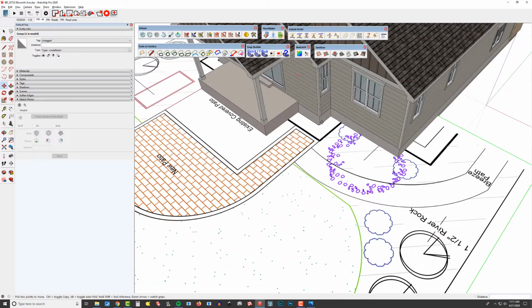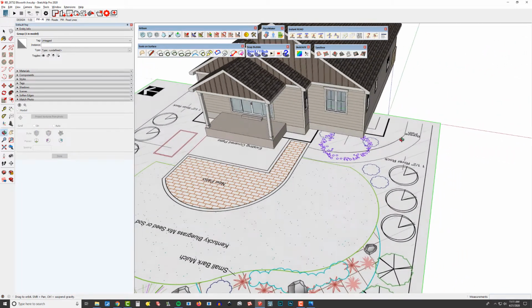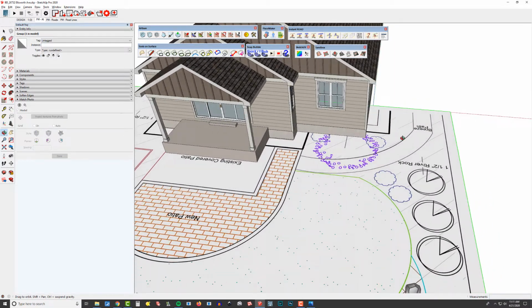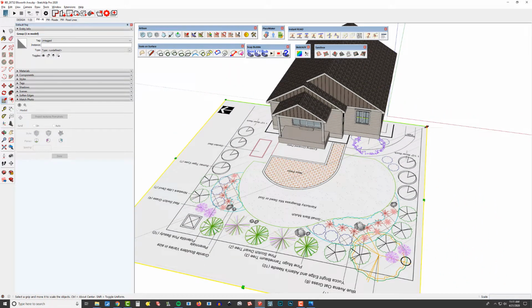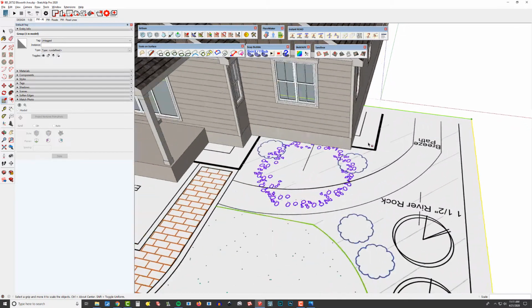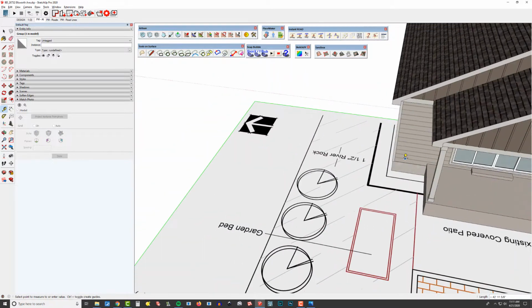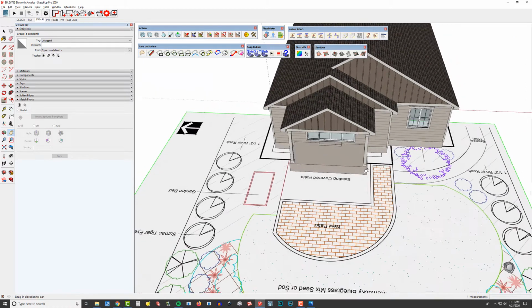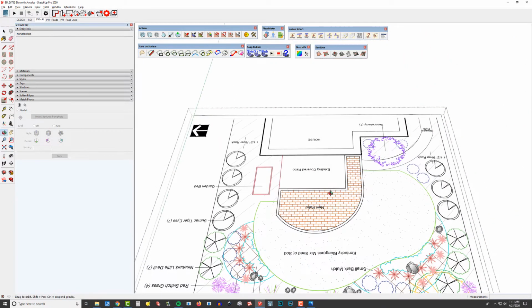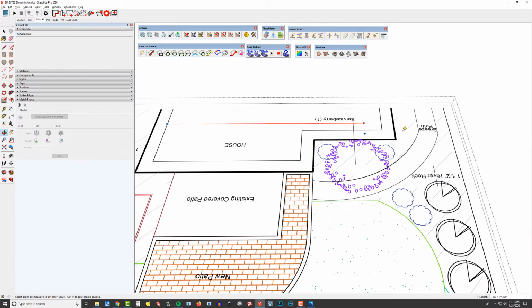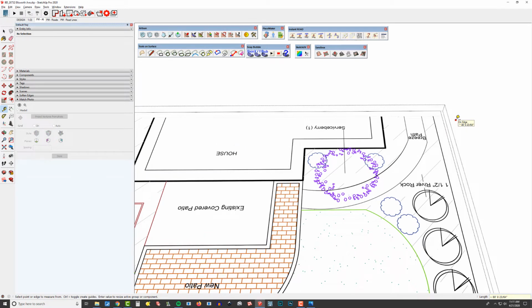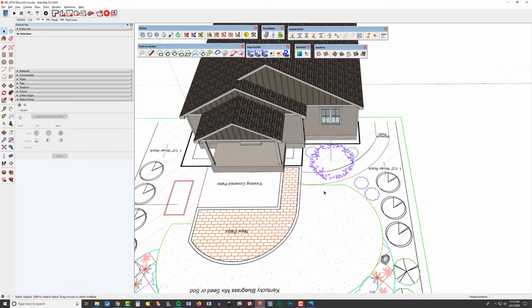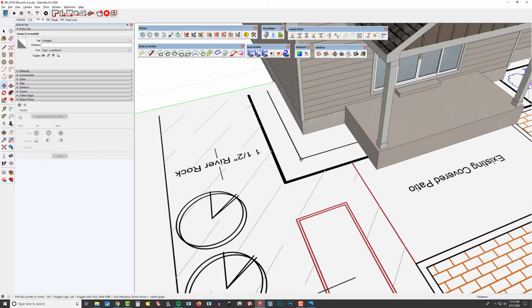And you can see now that this is lining up perfectly. I mean, it's not quite exactly where I want it. So maybe I'll scale it down a little bit. Let's do it again. Let's go from the whole house, a longer dimension is better. So we'll call that 44'8". All right. And so now I'm going to go in here, hide the rest of my model, and measure from here to here like that. And I'm going to type in 44'8", enter. And so we're going to resize it again. So now this dimension should match perfectly. And so we'll scoot that into place.